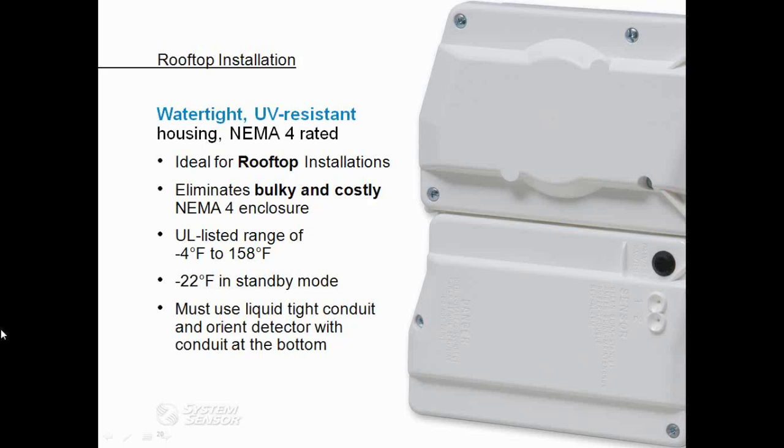If in standby mode, which, as we know, duct smoke detectors primarily sit in most of their life, it is approved for temperatures down to -22 degrees F. Though there are areas of the country that definitely do get colder than that -4, there should be conditioned air that's moving through your detector.